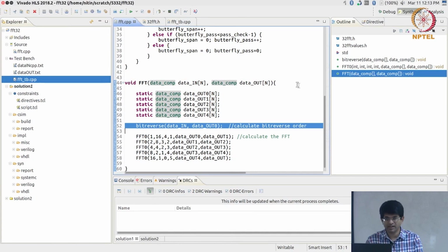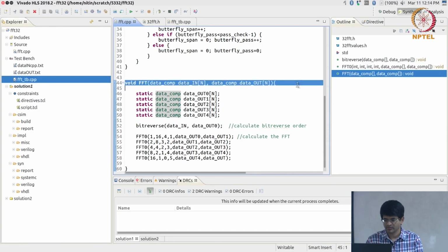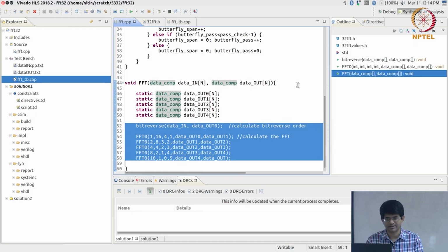The important thing to keep in mind, which in general is a good thing for all of you to keep in mind when you are writing code, is to see how we are structuring the code. We have one function which in turn calls a bunch of other functions. Broadly, you can think of it as each function becoming a module in Verilog. So, in some ways writing these functions inside functions is overhead. It is actually introducing a lot more modules than are required, but this is the whole principle of hierarchical design. Understanding it and making modifications becomes easy. So, I would strongly recommend you write your code like this.